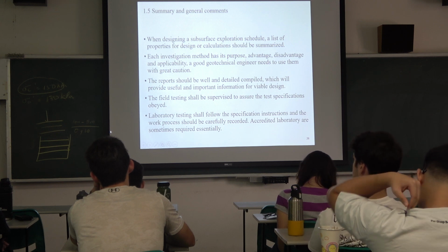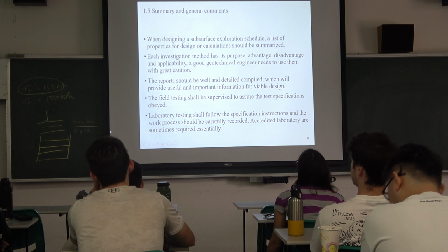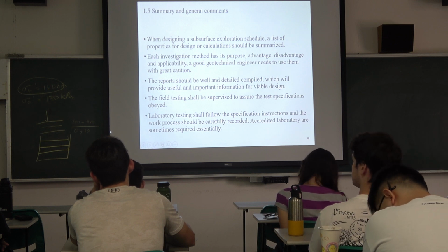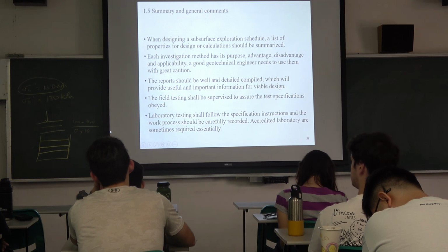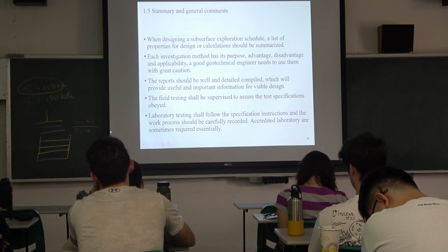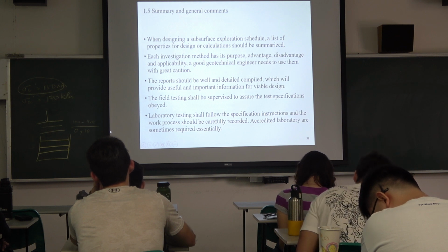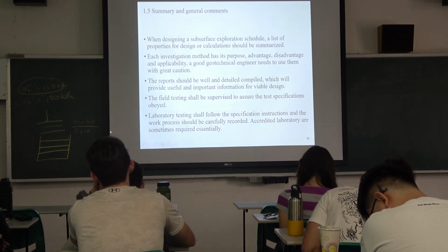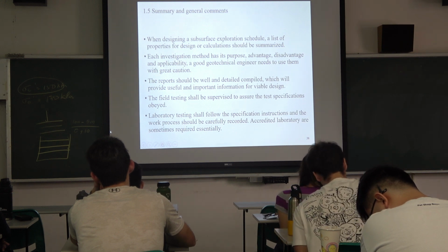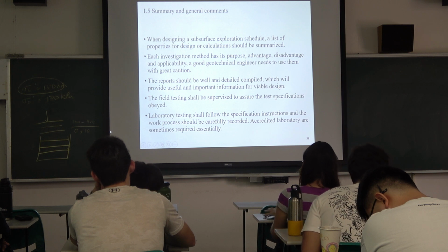The field testing should be supervised to assure that test specifications are obeyed. Most of the time, you don't need to do the test yourself. You oversee people who are doing it. But they typically don't care much. They want to do it as quickly as possible. So you need to make sure that you oversee them and that they do it to the required standards. And then laboratory testing should follow the specification and instruction, and every work process should be carefully recorded. And then accredited laboratories are sometimes required essentially.